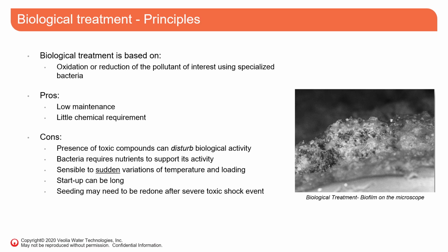The main cons of biological treatment: first, if there is a toxic compound, it can disturb biological activities. It won't necessarily kill everything, but it will inhibit the biological activity, thus reducing the efficiency of the process. Second, bacteria require nutrients to support activity. It's a living thing, so it needs nutrients, and you need to make sure these nutrients are in the water.